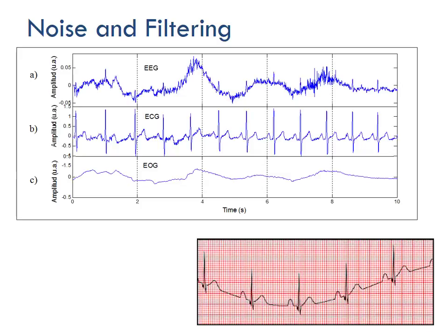The next one, ECG, electrocardiogram. The electrocardiogram is another signal. This one looks a little bit cleaner. There's still a little bit of noise in there, but you see those high peaks? In biomedical terms, you have something called your PQRS complex, and essentially it's just different parts of the heart polarizing or beating and depolarizing. So you get a positive when it beats, and then it has to come back to negative, back to normal. So you get a rest stage where it dips down.